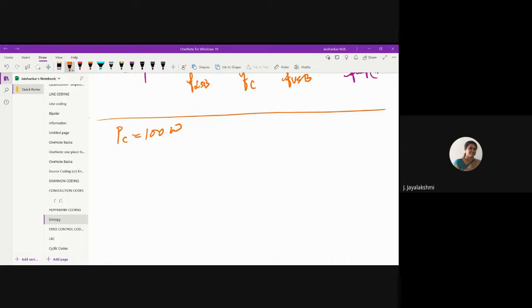That is modulated simultaneously by 3 modulating signals, and the 3 modulating signals have 3 different modulation indices. The 3 modulating signals are M1, M2, M3, and their coefficients are given as 0.2, 0.4 and 0.5. So these are the modulation coefficients of the 3 modulating signals, and together they are going to get transmitted.